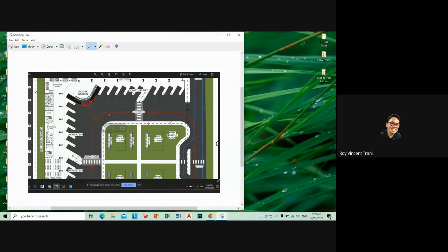So I'm worried that if they do it at the same time, there's a chance they will collide. So just to remove that possibility altogether, you just remove one bus, either this one or this one. You can keep one, but not both. And then you just reduce the road width to 4 meters here, and this is another 4 meters. So you have all of that space to add more rain garden system, concession spaces. You can develop that further.